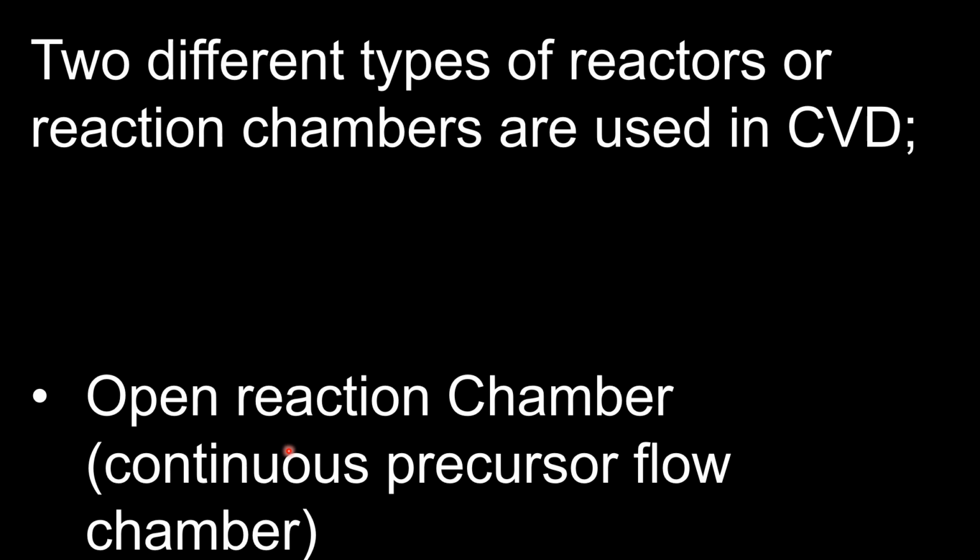On the basis of that, you can check how much precursor material is introduced inside the open reaction chamber. So in that way, from outside, you can introduce a precursor material inside the reaction chamber, and in a controlled fashion you get a chemical reaction onto the surface of the substrate, and at the end of the day you get a thin film deposited on the surface of the substrate.